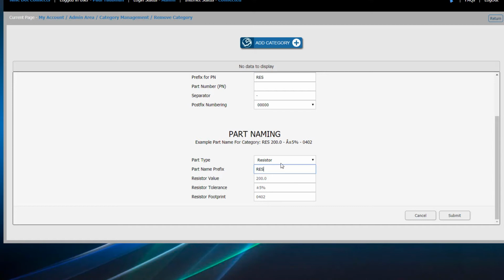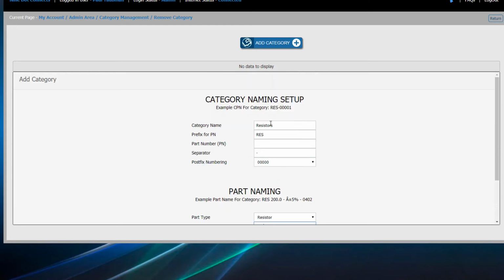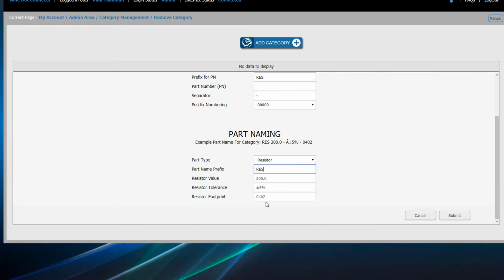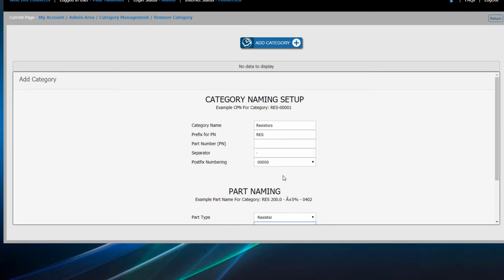And what's kind of nice about this is that it's okay to have duplicate names because we actually have a specific company part number set up over here. So in your library, when you're looking for it, you're going to be able to see all of these resistors with these values, and if they happen to have the exact same thing, that's okay because again, there is a different unique ID that represents those, which allows that to happen.